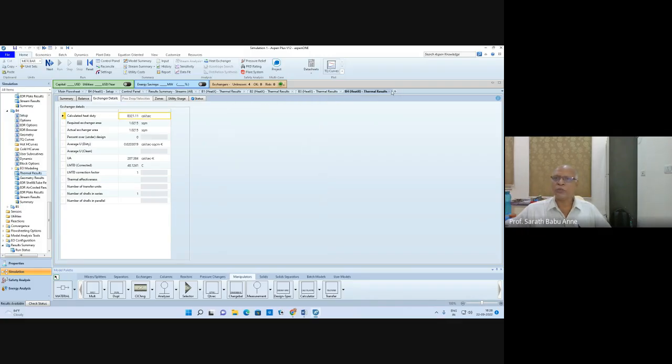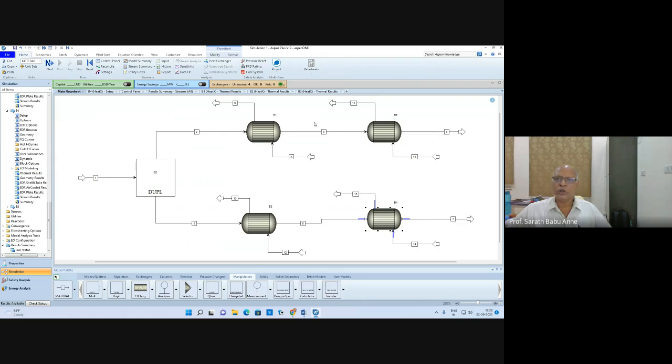In addition to this particular problem, do you think we assumed 50? Do you think this 50 is an optimum temperature that is going to minimize the sum of these two areas? Do you think this temperature is going to influence the sum of these two areas? Of course, in both options. Now let us try to look at that as well. In order to identify the effect of that intermediate temperature on the areas, I will be doing some sensitivity study.